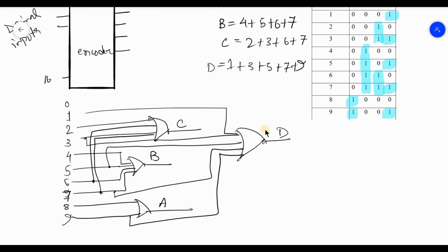So in this manner, we have developed the four output sequences A, B, C, D. So this is our decimal to BCD encoder. With this one, you can produce a pattern of BCD outputs from given decimal inputs.